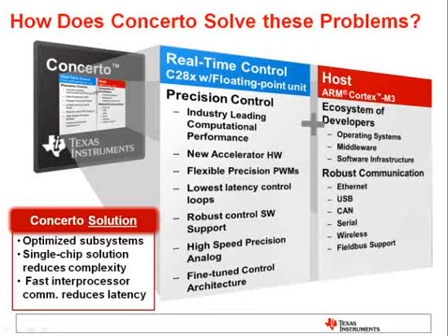On the host side, you'll find the tremendously popular ARM Cortex-M3. With Concerto, you can dedicate this core to the system management and communications aspects of the application. There's a slew of communication peripherals connected to the M3 as well, including USB, Ethernet, and CAN.